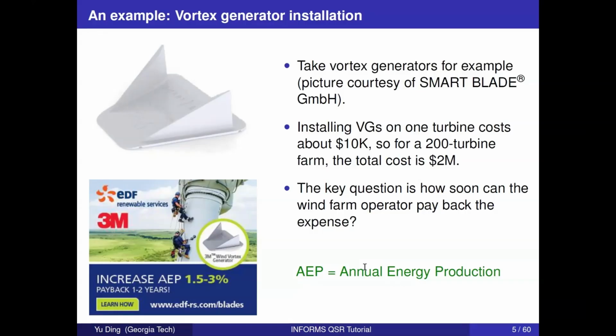And the theory says all these kinds of spikes will produce some local small micro turbulence, and that will improve the so-called lifting characteristic. And with that, you actually can improve the power production efficiency, even if the blade is not of the optimal shape after a number of years of service, right?